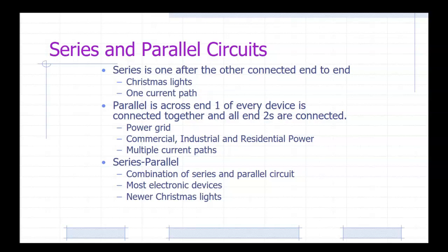Now, why is everything also wired parallel? Well, because if one bulb goes out, all of them don't go out, right? But they all go back to the same circuit breaker. So parallel is how we wire individual lights in a house. Again, if, let's say, this bulb right here goes out, the whole row won't go out. It actually takes something else to do that.